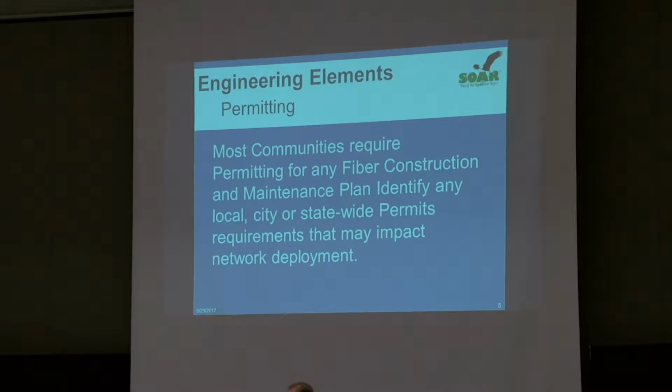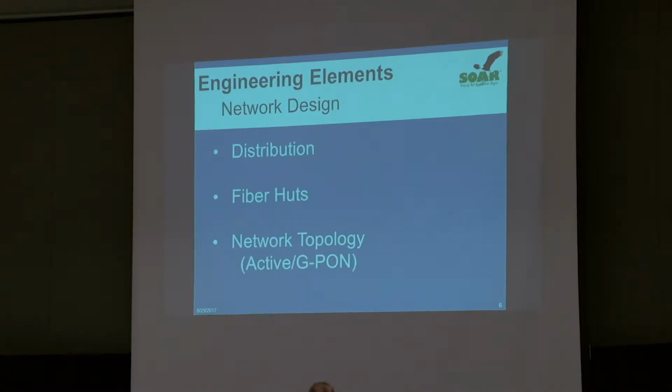Well, that's exactly where we need to be. So each one of these slides isn't inclusive of the entire process, but touches on some of the most critical components of fiber design and network management, permitting being one of them. Network design is where you go out in the field and engineer your distribution areas, your fiber huts, and your network topology, whether it's active or GPON. All of this we're going to talk about a little bit later as we go forward.